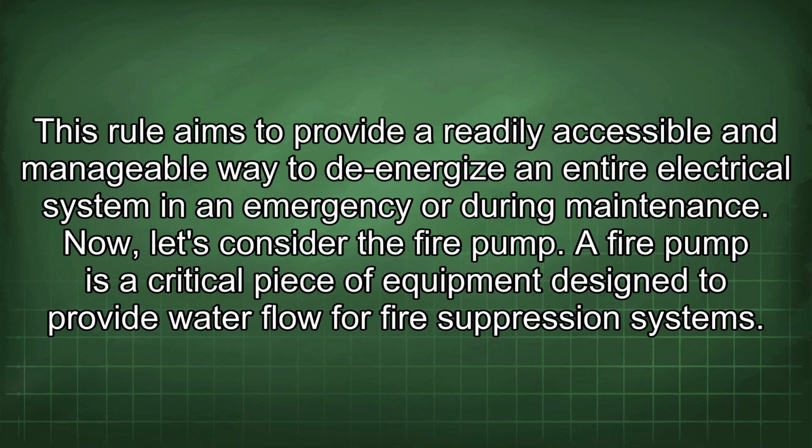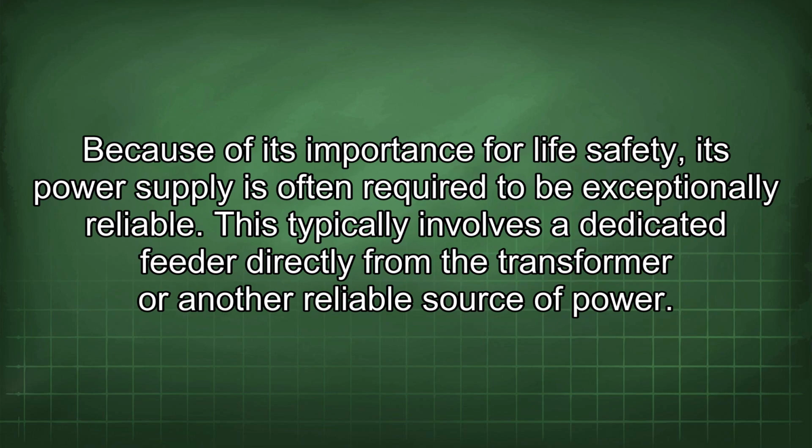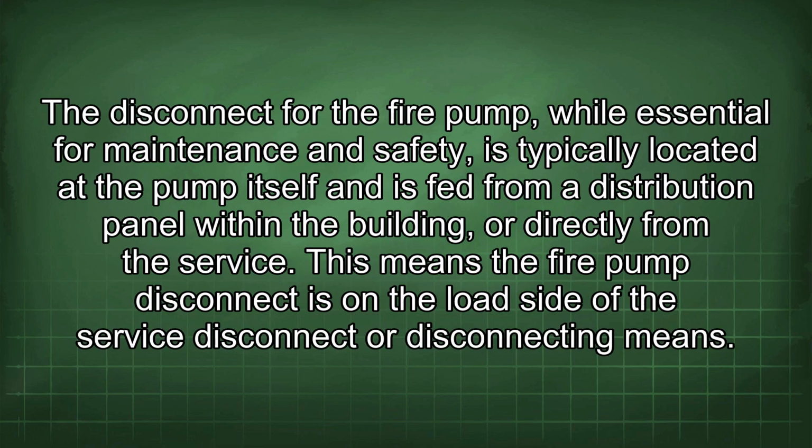The fire pump is a critical piece of equipment designed to provide water flow for fire suppression systems. Because of its importance for life safety, its power supply is often required to be exceptionally reliable. This typically involves a dedicated feeder directly from the transformer or another reliable source of power. The disconnect for the fire pump, while essential for maintenance and safety, is typically located at the pump itself and is fed from a distribution panel within the building or directly from the service.